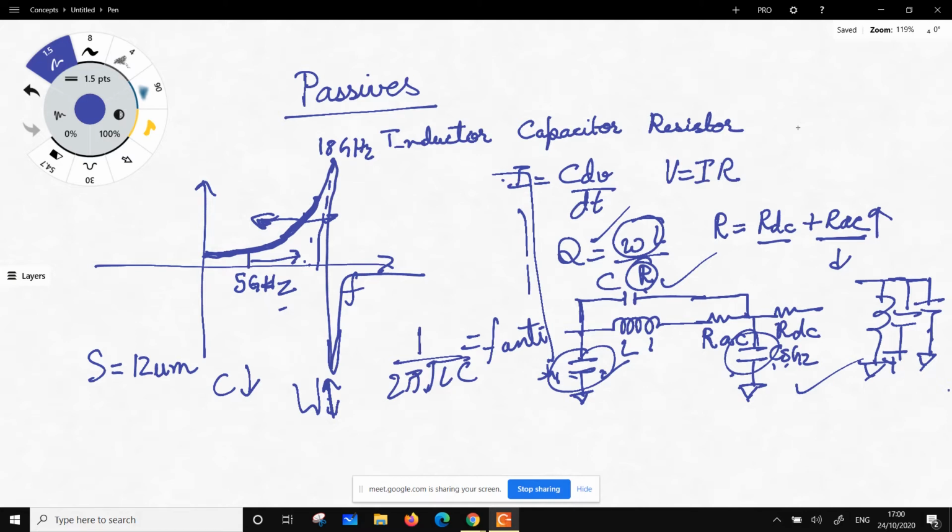Okay, so that's the difference between using the inductor in series and using the inductor in shunt. Using the inductor in shunt, CSH1 or 2 comes in parallel with C, and that ends up in parallel with L, right? So its anti-resonant frequency is lower than in series. Okay, so if you use the inductor in series, you have to reduce C, then the only way you have is this one.